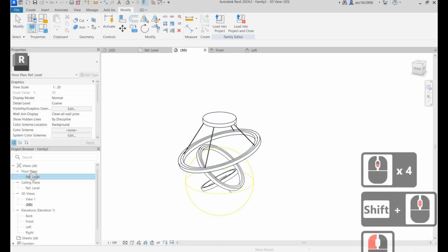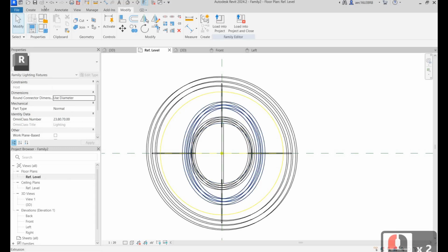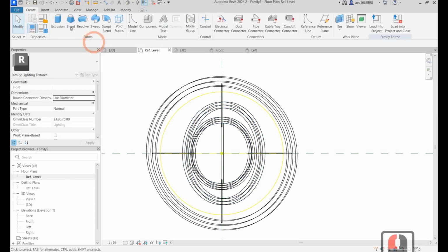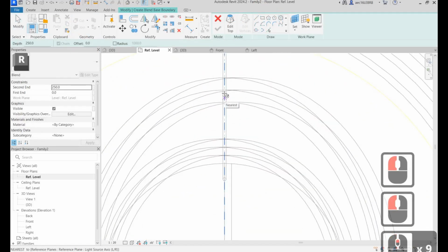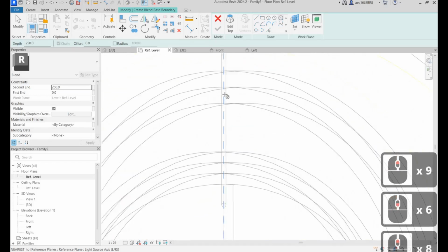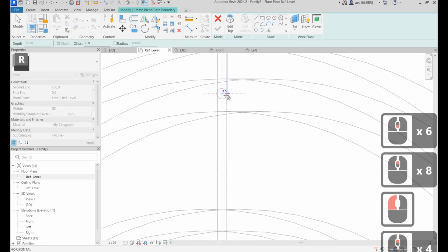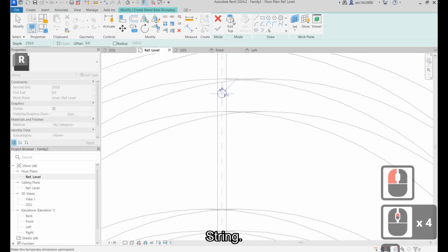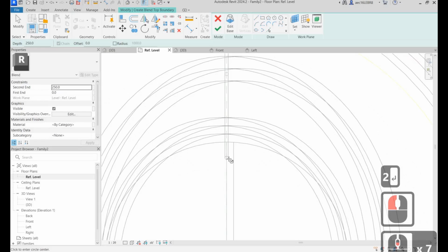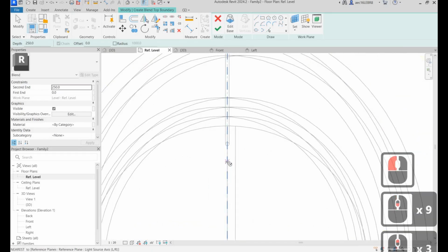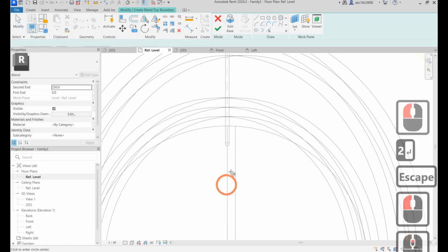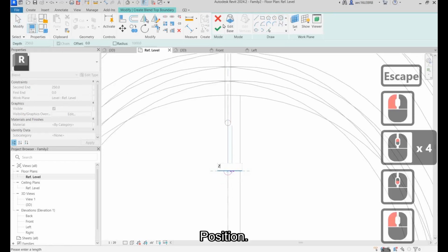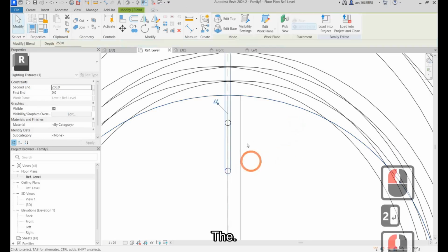Back to here. Now let's try this ring over here. Try to create blend again. Then from here, now we can see this ring is somewhere. It's quite confusing. Somewhere, let's say over here. Let's make it 2 mm. Okay, edit top again. Top will be somewhere here. 2 mm. Okay, zoom in. 2 mm. Okay, like this.